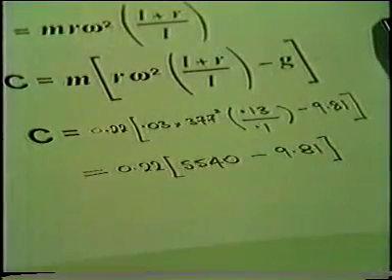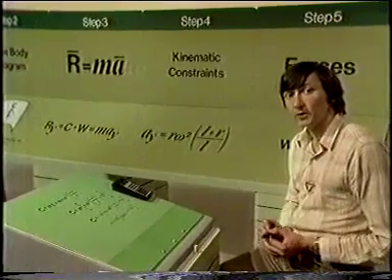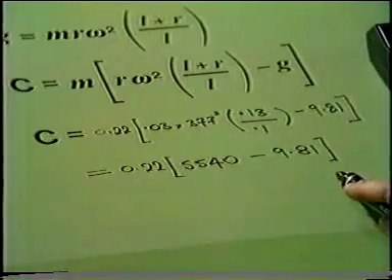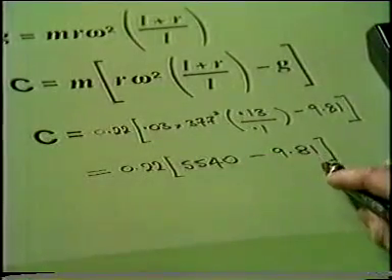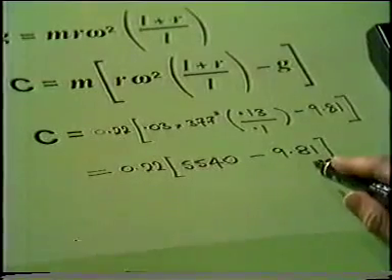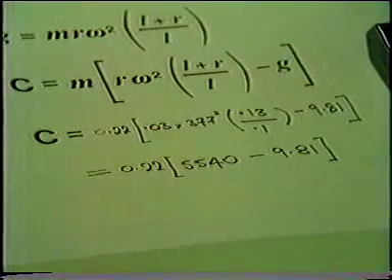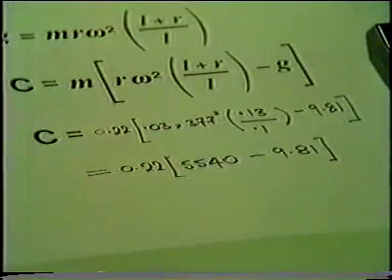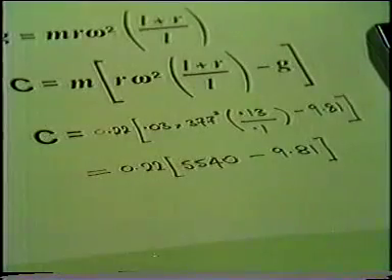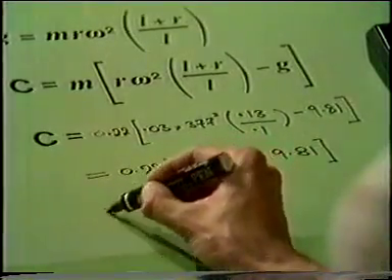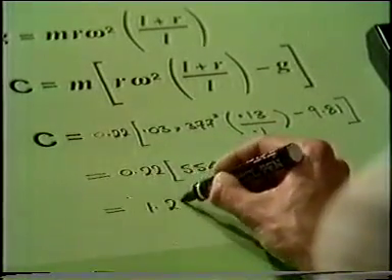Right. Before we continue with the evaluation, there's something which I'd like you to look at. Look at the relative magnitudes of these two accelerations. In fact, the contribution of the weight force is virtually negligible. 9.81 is about a 500th of the acceleration due to the actual kinematics of the mechanism. So in fact, back at the free body diagram stage, I could quite well have neglected the weight force and only included C. If I go on to evaluate, finally, it turns out